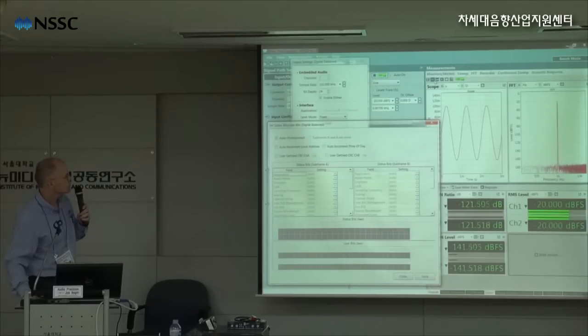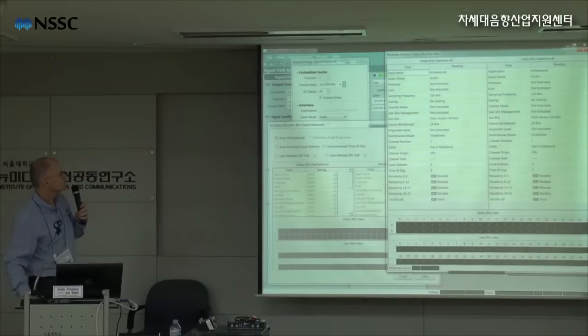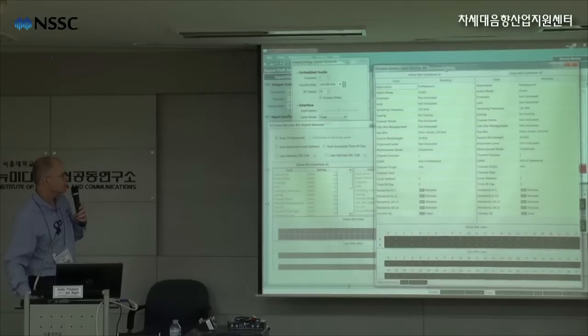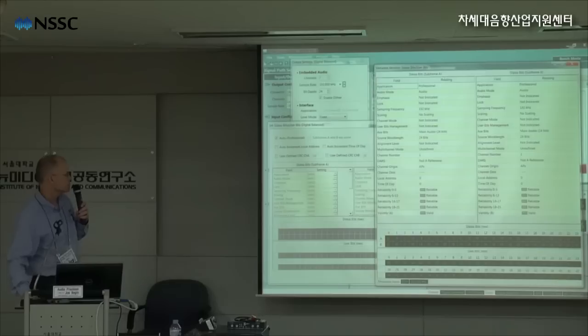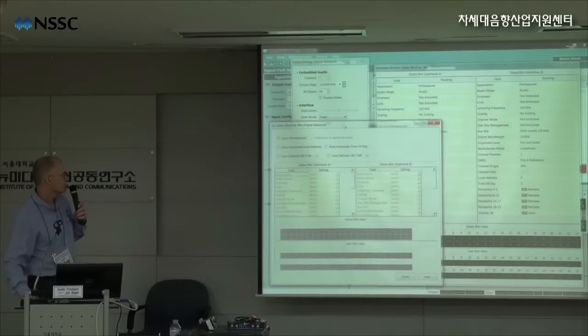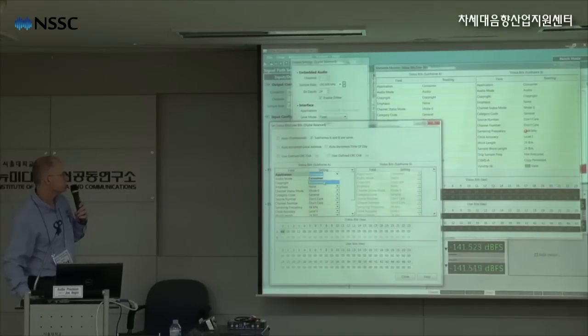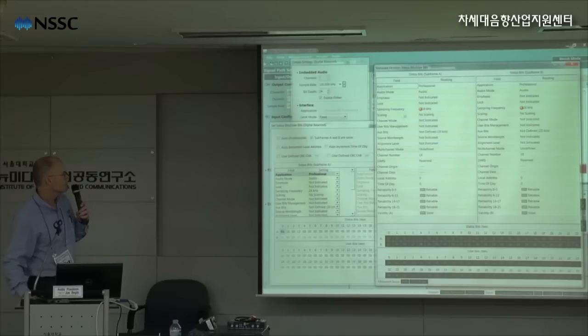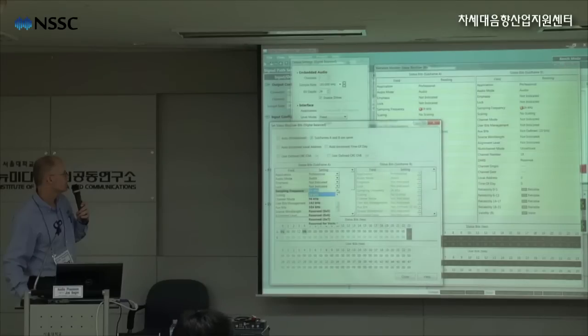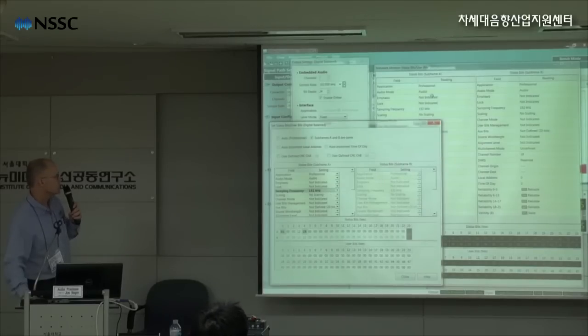There's also a meter over here, which is for the digital input side. And this is metadata that's carried in those user bits and channel status bits that occur in those channel status blocks of 192 frames. So if I uncheck this, you'll see here we have access to these fields, and I can change a field here, like change this from consumer to professional, and we're getting an indication that the sampling frequency is incorrect. If I change the sampling frequency to 192K, now that indication has gone away.